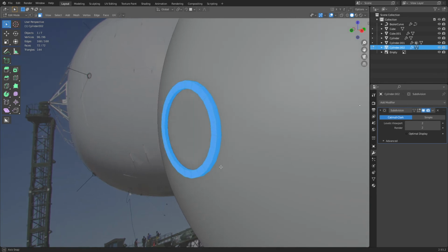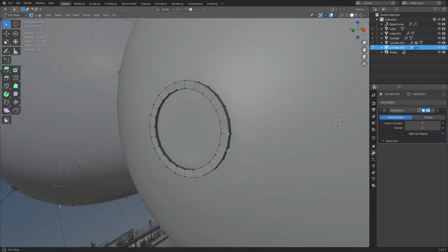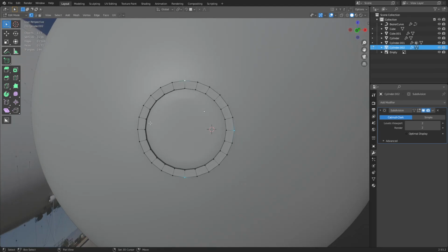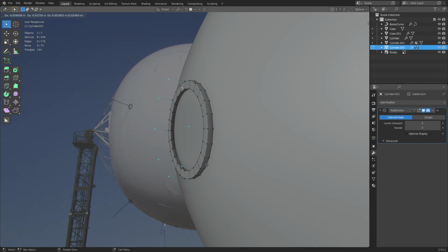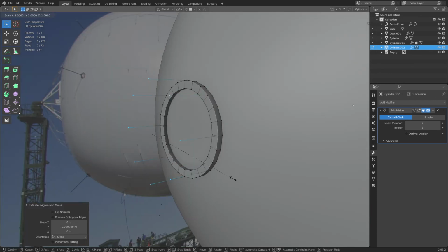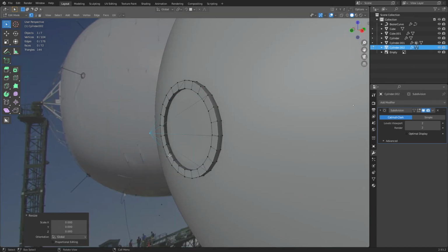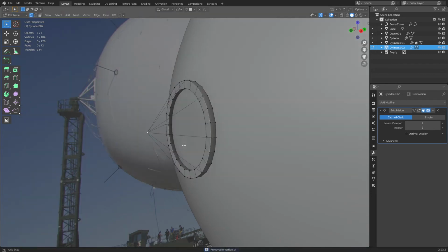And then, this is going to be fun here. I have no interest in modeling all this, but I'm going to press basically E on these vertices. Extrude them out like so. S 0. Select that point. Press M, merge by distance. And it didn't merge any of them.